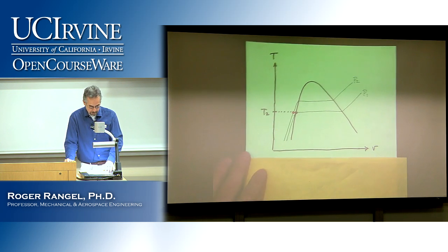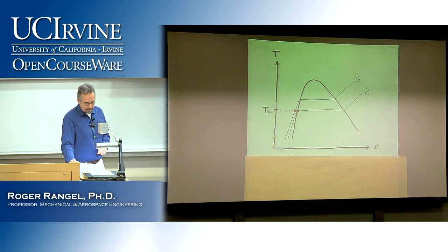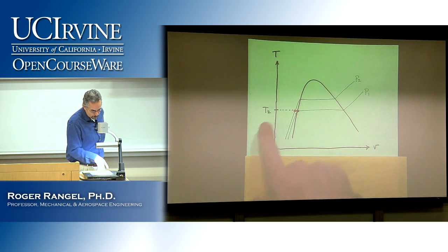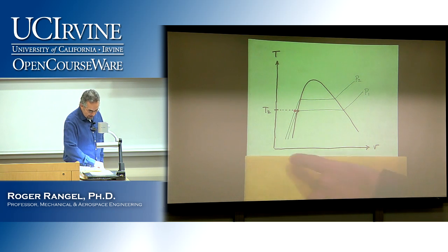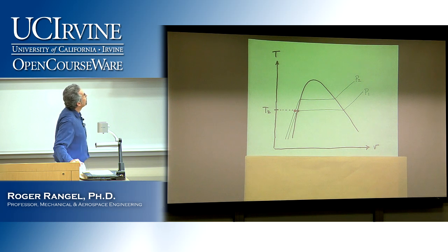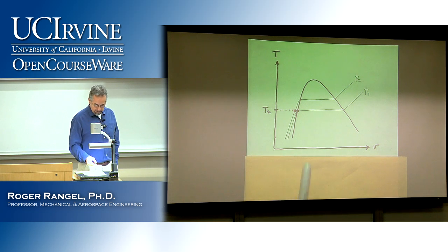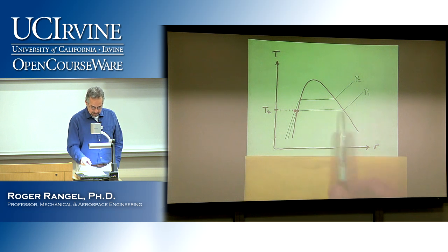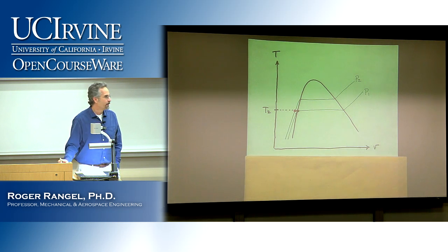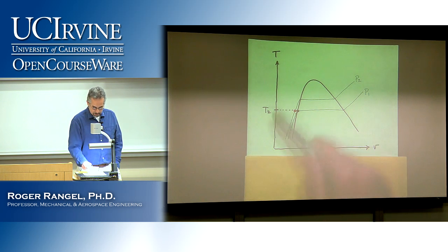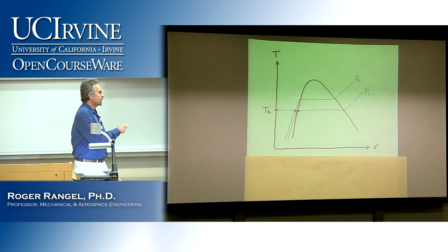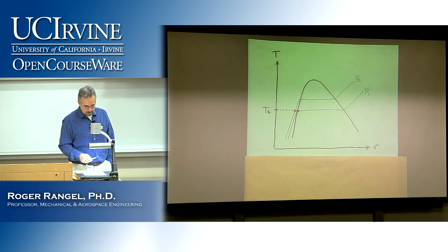My real data point is the red dot. It is at a temperature T2 and at a pressure P2. So obviously, if I try to go into the saturated table with T2 and P2, I'm not going to find anything because there is no such entry for P2 and T2. P2 and T2 give me a point that is in the compressed liquid region.